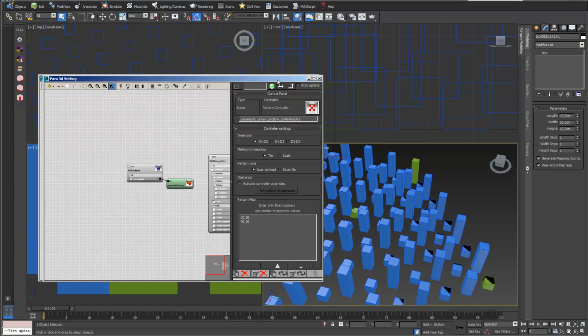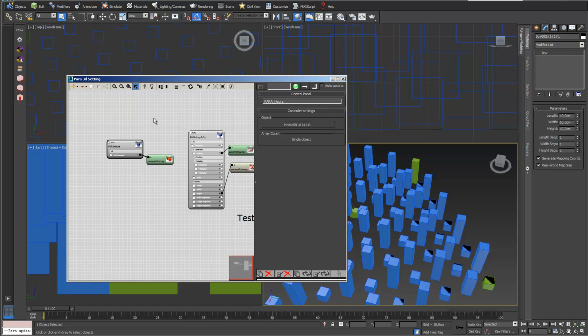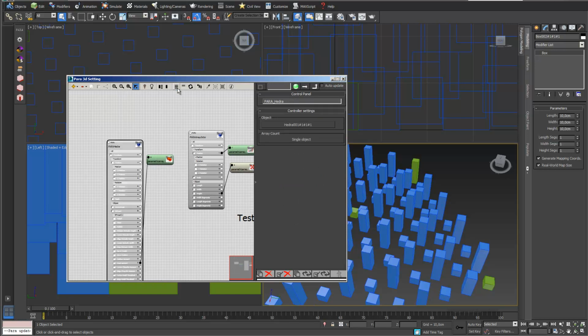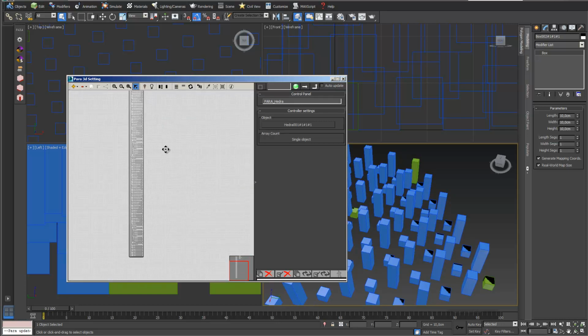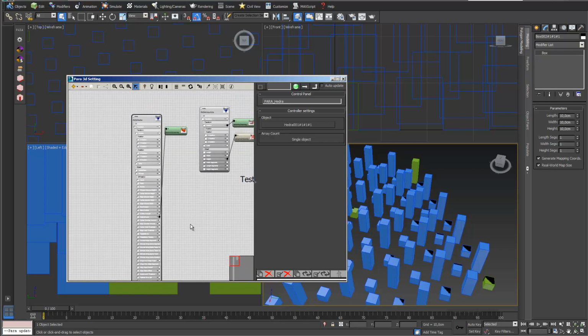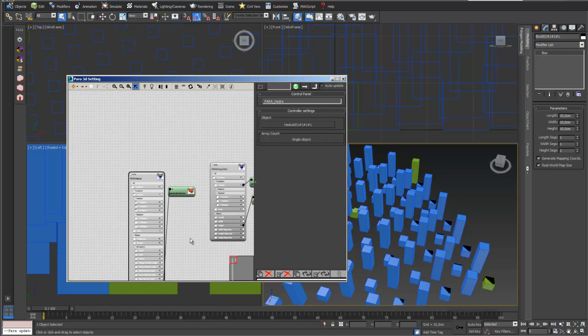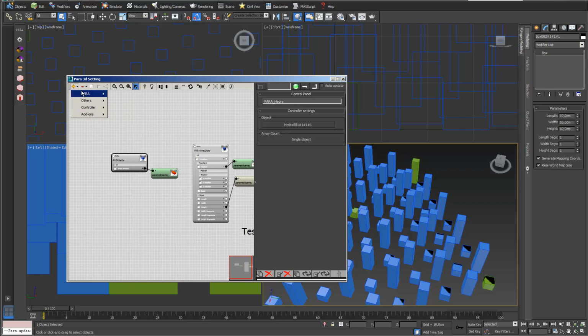As my second example, we just play a little bit more with this Hydra, and I go into show all channels, and we see how many elements I can already use, and this doesn't help much, so I go again into a right mouse click and say filter unused channel. And we can also add elements.